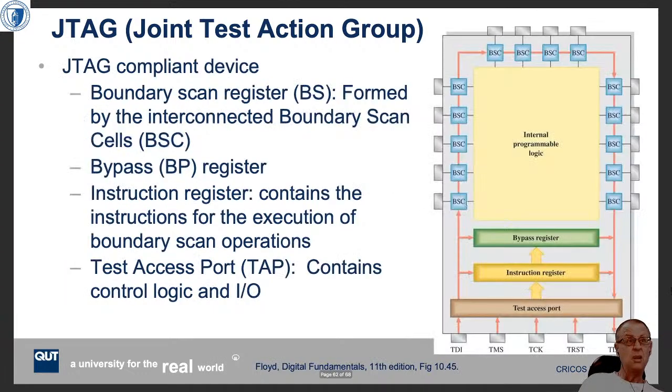To get to the next page, right? So the thing is, it only looks around the boundary of the device, right? So the big yellow block in the top here is the logic, and then all of the connections around it have what's called a boundary scan cell there.